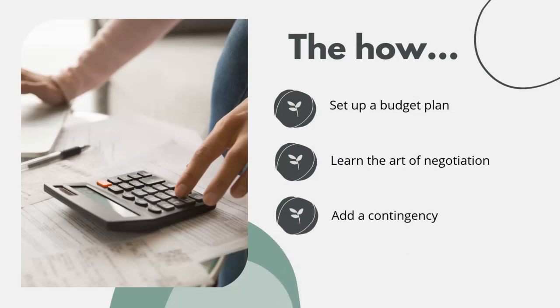My last tip for this section, allow for contingency. I always allow for a 10 to 15% contingency. When working on any design project or building or renovation, no matter the size, there's always something that is going to come in slightly out of budget or something that you might have forgotten. So to avoid this, I always add my 10 to 15% extra contingency fee at the end of my project on my mini project budget.